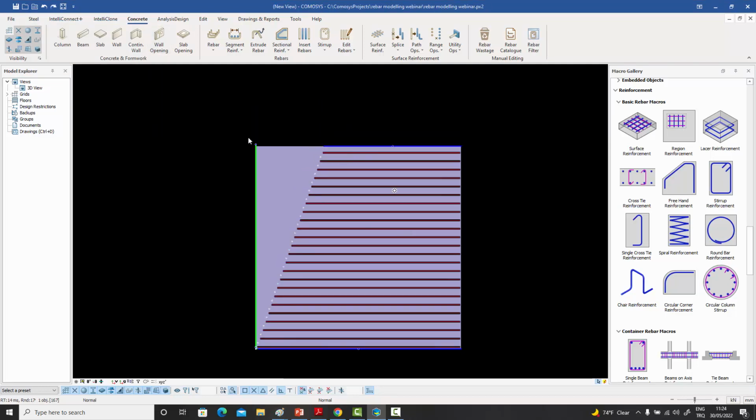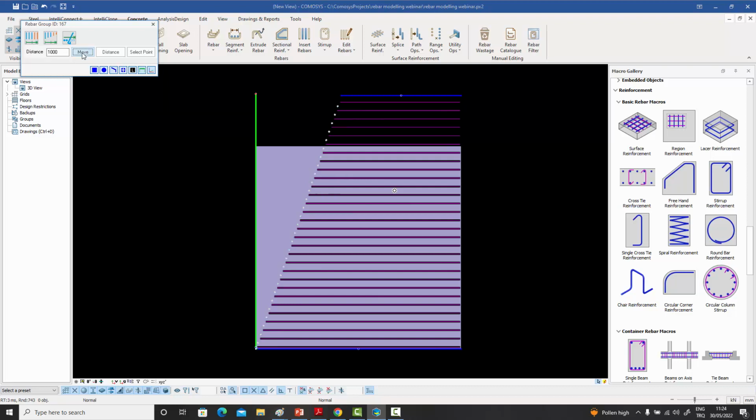And let me do the same thing again now, but with the other command. Let me select the end. And instead of using this one, I'll use this range extension. And when I use this one, then instead of this point moving upward, it will move along this taper. So let me do that. And now you can see that it is moving along that taper. And both of them can be required depending on what your needs are.